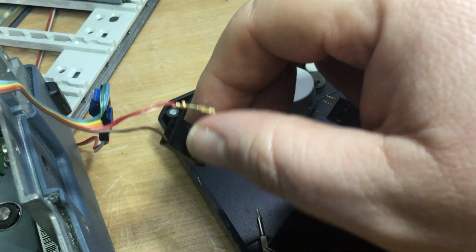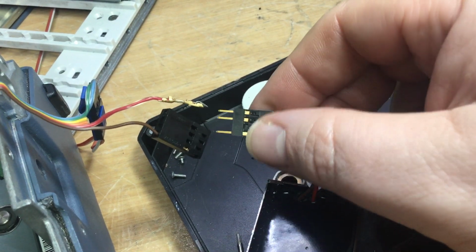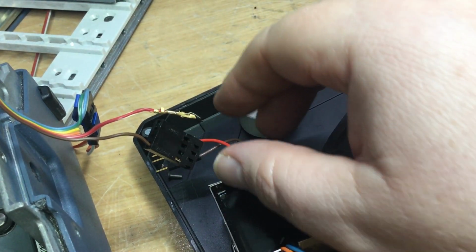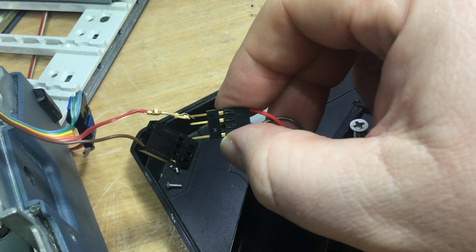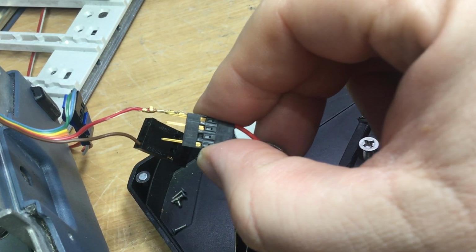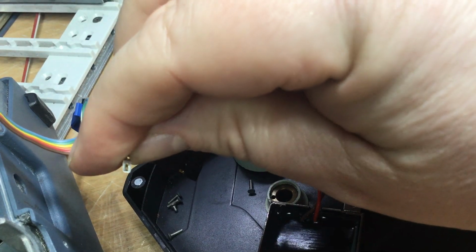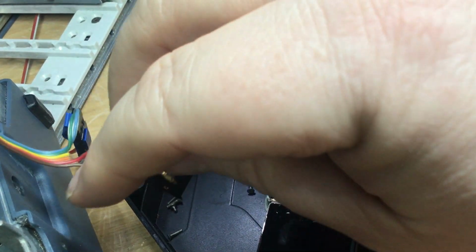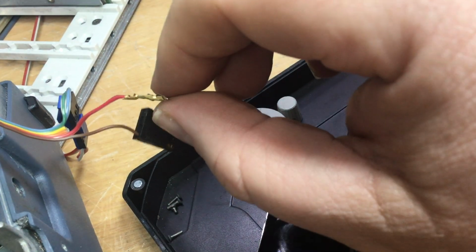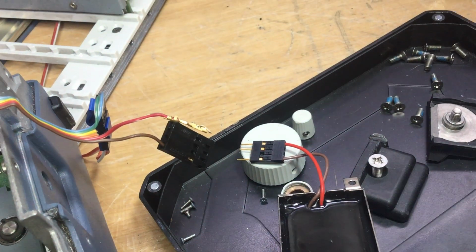So I've just backed this pin out of the socket, which this connector mates with. Notice this little bit of metal here was bent out of position, so I just bent it back, because the pin actually goes into it at that angle. There's a tiny little hole in the top that it goes through, and it pinches it. So I just squeezed it together a bit, and then we'll reattach that back into the socket and see what happens.